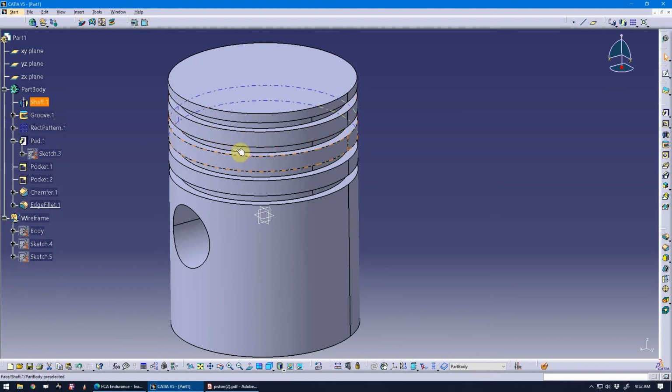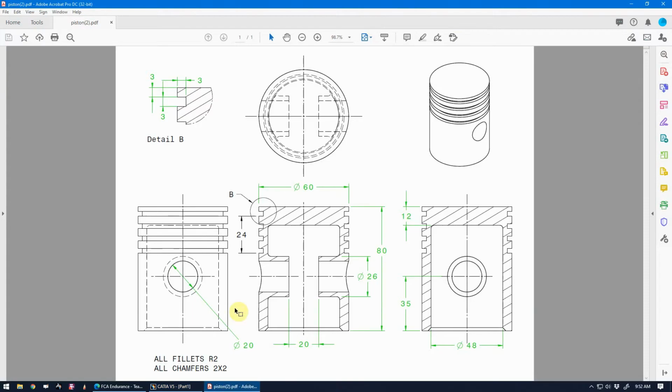And then I wasn't really thinking through at first the pattern parameters. As I was looking at my drawing, I started thinking, okay, so I've got a 3x3 groove, 3 from the top, and then I started thinking, well, it's got to be 3 spacing. And then I did that, and then I started thinking, well, that's not right. And then I went and looked at the drawing. I noticed it was 24. I've got my 24 parameters. So that's telling me what we're needing here will be 4 instances, 1, 2, 3, 4, over a total length. And notice how this length is going from that point to that point. So that's a total length of 24.